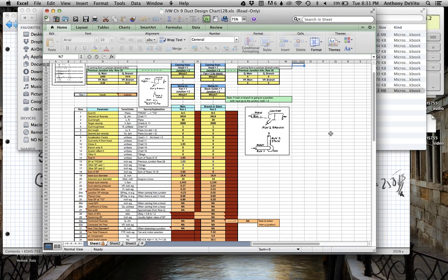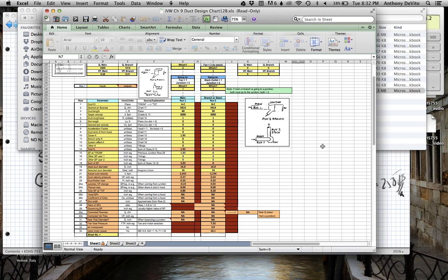Oh, no, when we're working with a lab hood, you're putting your hands inside the hood, right? So a laboratory hood is different. But this, I'm just giving that as an example of what kind of velocity I might want as a capture velocity. But you might want to research it, see if somebody else recommends what velocity you might want. It's going to be very specific to the material that you're working with.